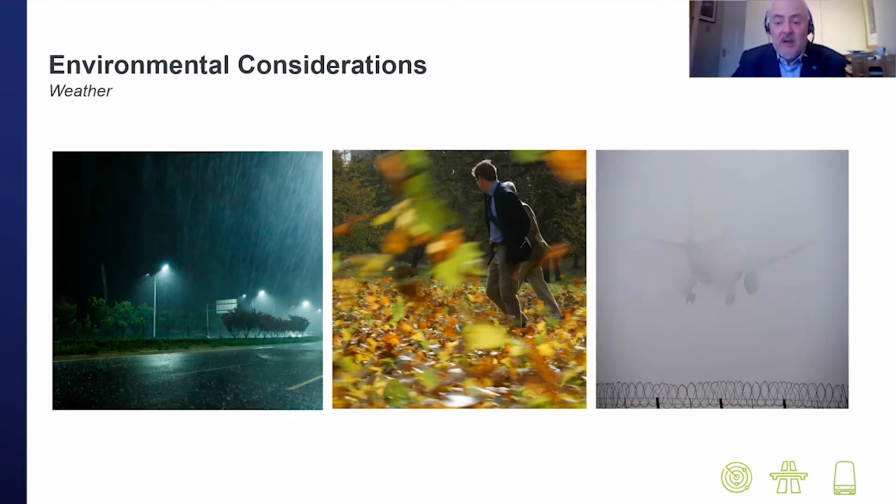Although radar is regarded as an all-weather sensor, heavy rain can cause some attenuation of the transmitted power reaching the target, and it can also produce backscatter of the echo that is reflected back to the radar system itself. It means there's less energy received, so it's important to ensure that any system specified has enough but not too much power to get a usable echo from the target at whatever range is specified by the client, and also a well-designed antenna to allow adequate detection.